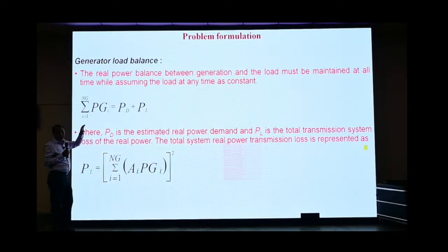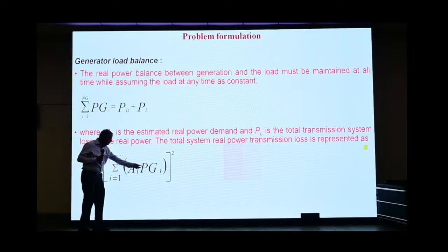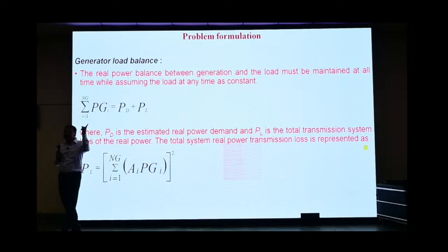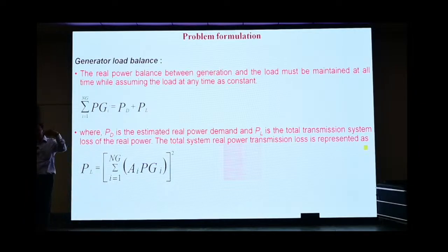I have already told you our electrical power system is such that total generation must be balanced by the demand, provided that the transmission lines are lossless. But actually some losses are there. The loss factor, or whatever losses in the transmission line, depends upon the generation. If the three generators are generating differently, losses will be different also. You see how complicated it is.